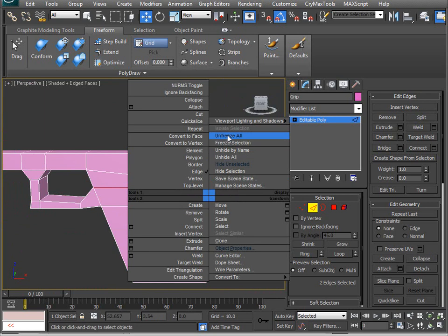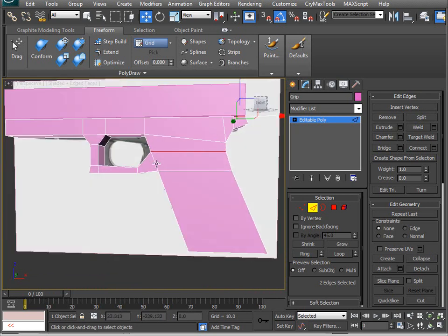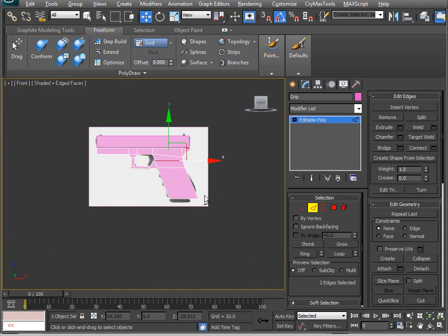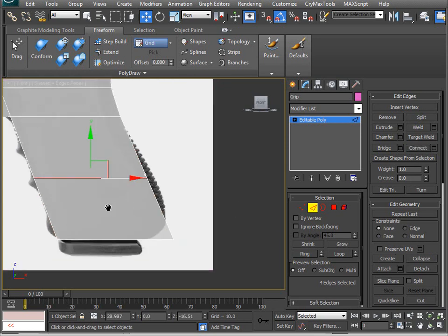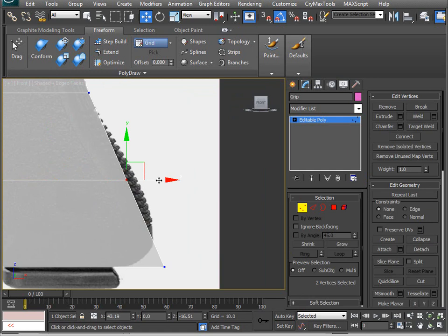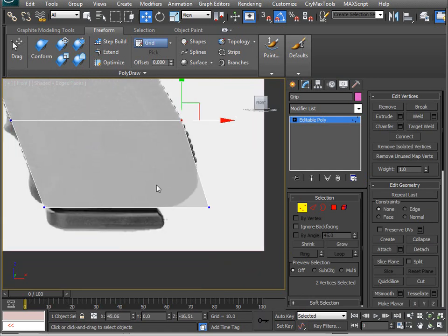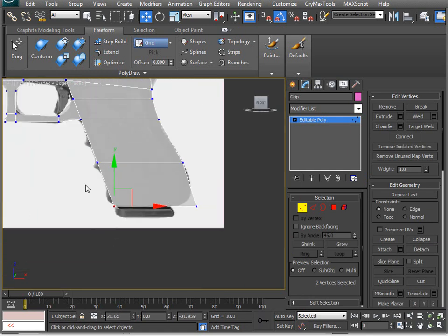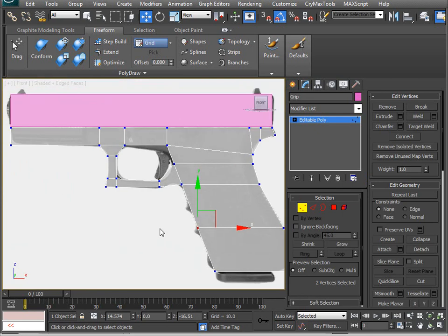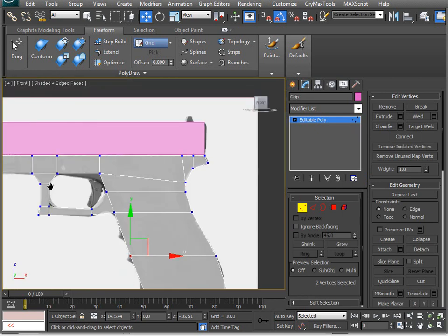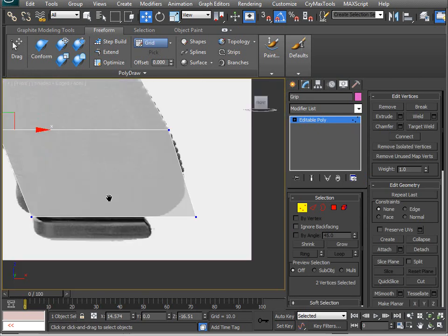Okay, so unhide all. Get back to where I was. View F, and I'm going to hit Alt X to get back to invisible. Now I'm going to start cutting in a couple of these. I'm not going to go too far on the LowResMesh, just because it's unnecessary to show the animations or how to animate. So I'm not going to go crazy. I'm just going to do the basic objects.